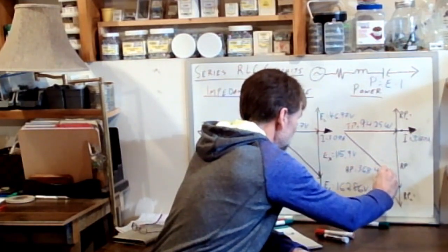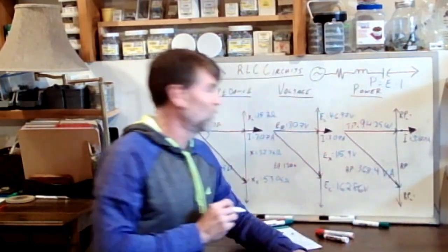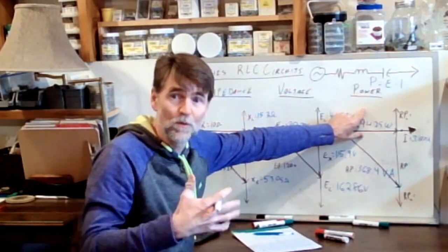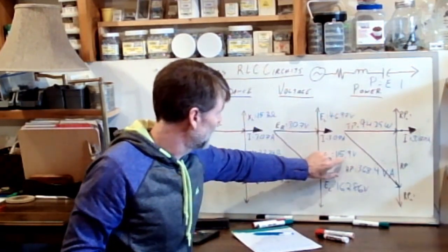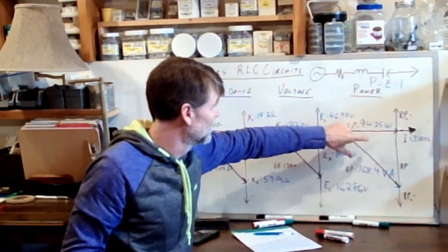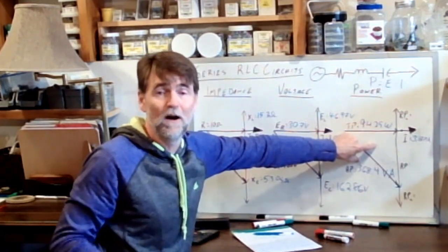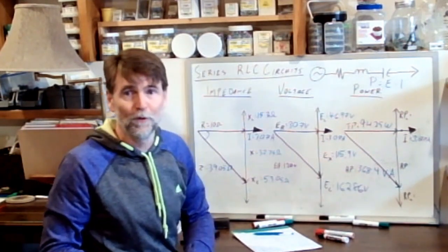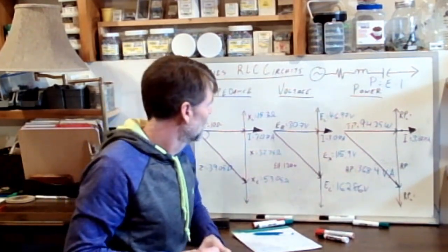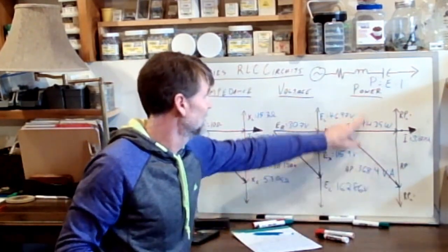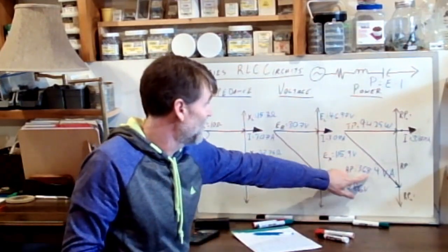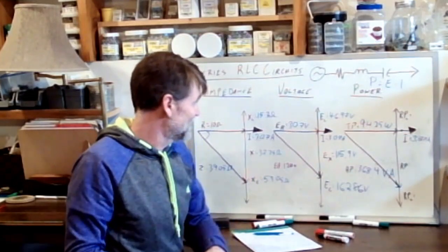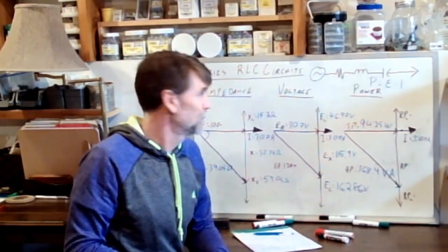Volt amps. Those are our volt amps. So our watts are the power that we actually use, the work being done by the circuit. Apparent power in volt amps is the demand on the power supply, the amount of power that we get billed for at the end of the month. So we can see it's not a very efficient circuit, is it? We're spending a lot of money on power for doing a considerably smaller amount of work.